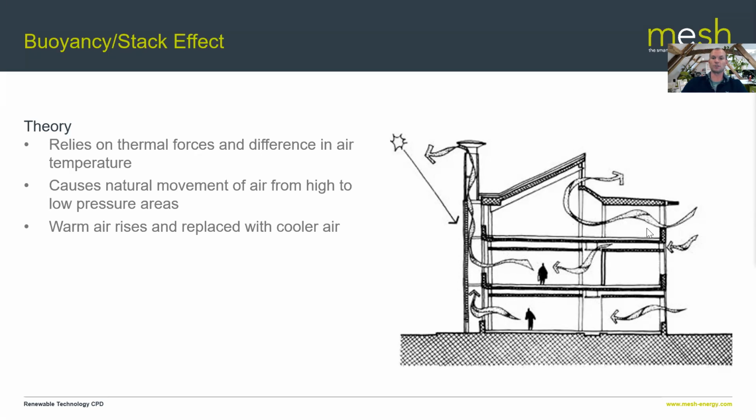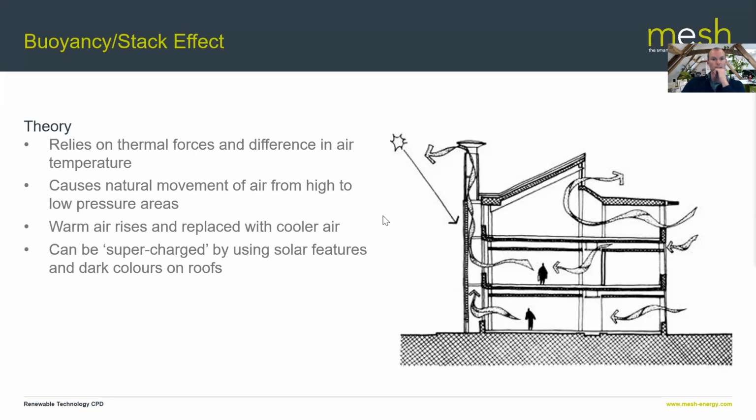And this little diagram shows exactly what we're talking about here. So you've got openings at the top of a building. This is a kind of chimney, but also you've got a high level opening in this building, and air is being brought in through doors and windows and naturally rising and venting through these two high level openings in the building. And because temperature drives this effect, you can actually supercharge it through design and